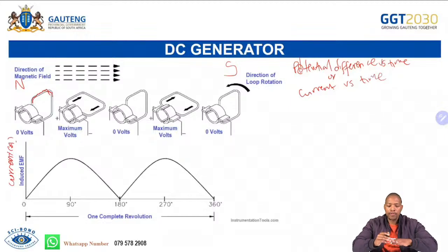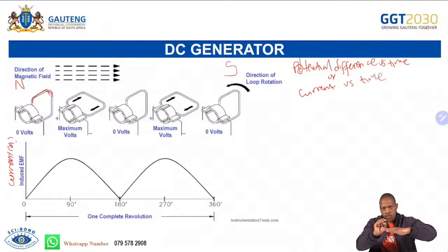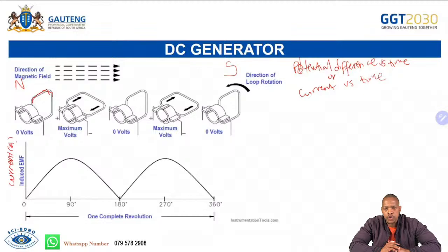However, once the coil starts rotating and goes to the other side, it cuts the magnetic field. From here, it has rotated 90 degrees to here. Once it cuts, EMF is induced, and maximum EMF will be induced there, at an angle of 90 degrees, as time progresses.